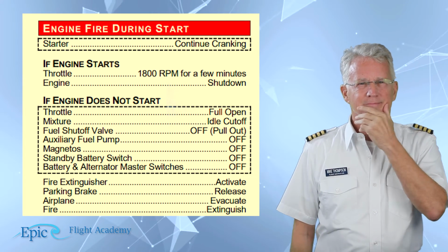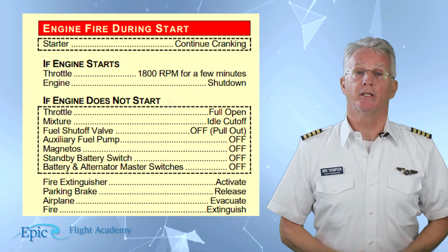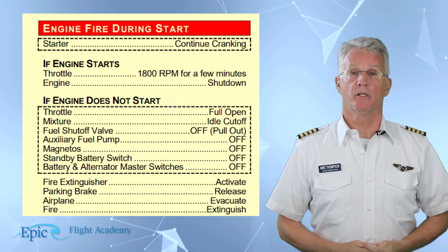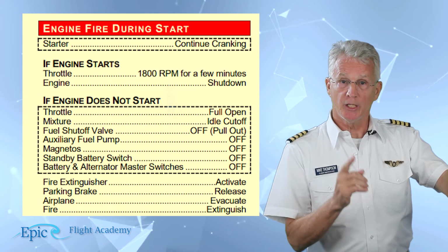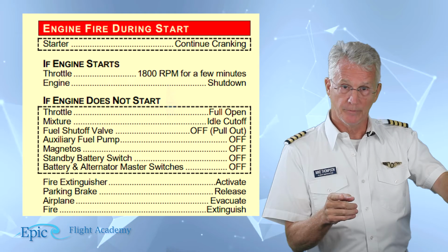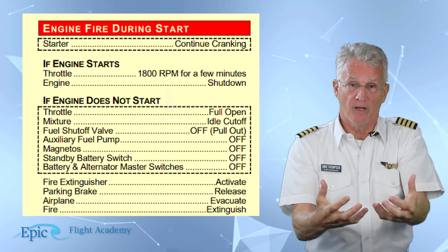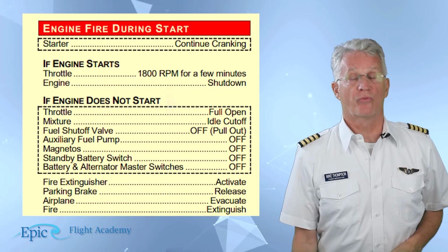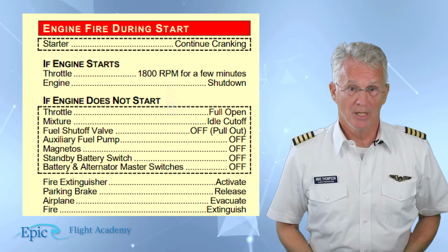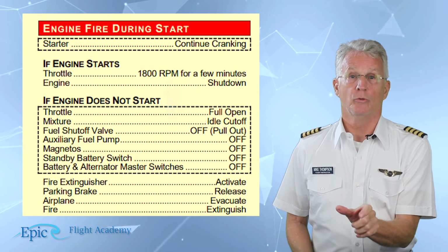Why is that? Well, because the first thing that you're going to do is to continue to crank the starter, turning the engine over. Now, we do this in an attempt to literally suck the fire into the engine. Notice, this is your first memorized immediate action item. Starter, continue cranking.